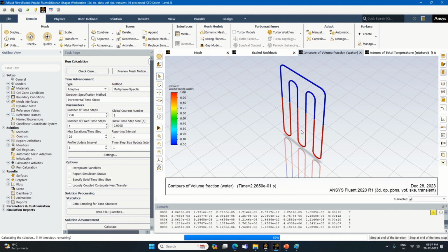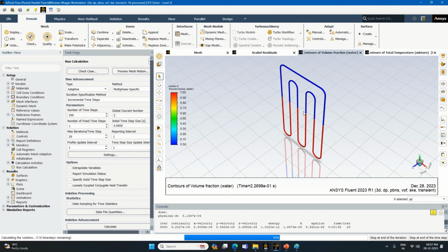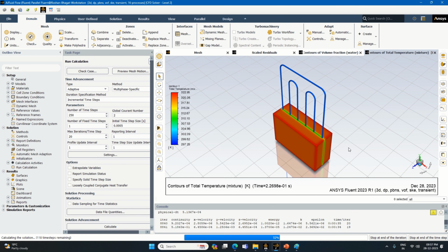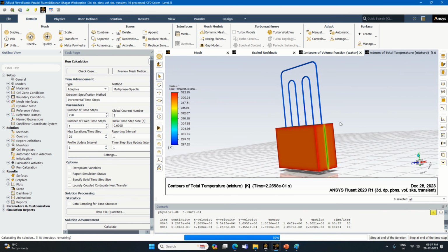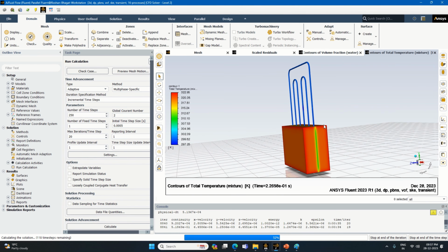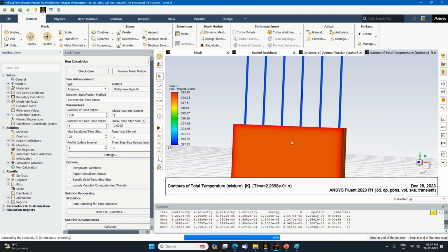It's maybe for around 24 hours or so, so as to get a considerable development of fluid flow and other things. You can see in terms of temperatures here, the variations can be easily observed on this window, but still that is not sufficient. We need to run it for longer time. As I said, only 8845, this will not be sufficient to observe the entire contour. So definitely it has to be for a higher number of time steps.